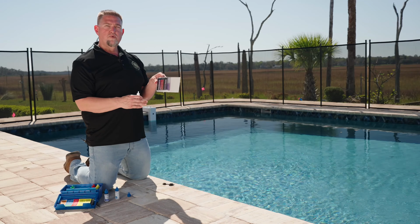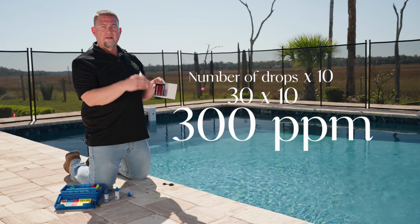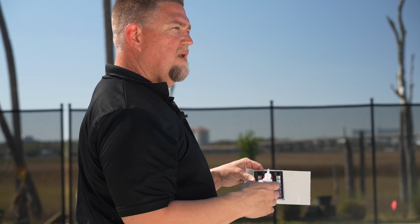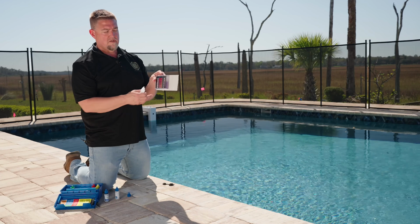If you have a fiberglass pool, again, calcium is important so it doesn't mess with your coping, your pavers, or your concrete, and you don't get the leaching from that into your pool surface. However, with fiberglass, you have a pH neutral surface and a smooth area, so you're not going to get too much scale buildup as long as your pH and your calcium levels are within range.